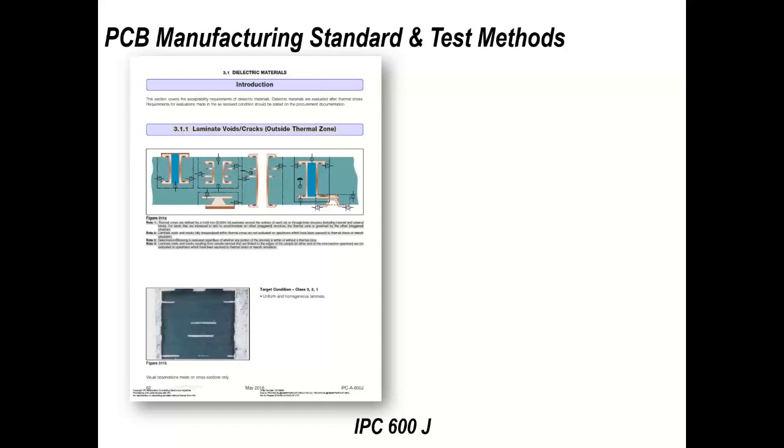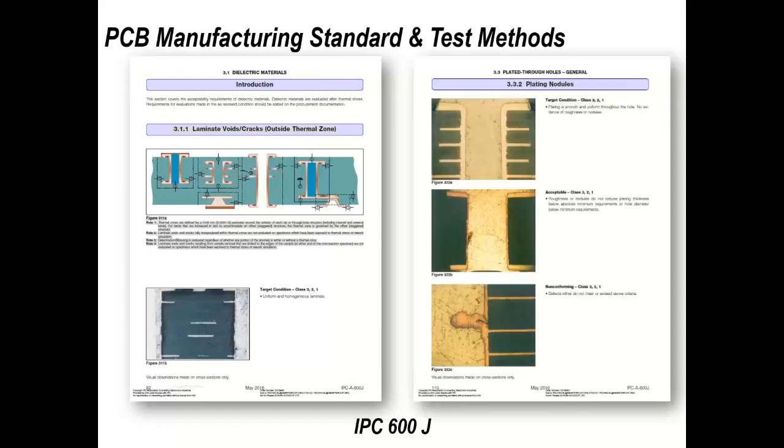You can take a microsection, which if you're doing it yourself, that's fine. If you're having it done for you, it may cost you 200 euros. You can then spend a lot more money re-grinding, re-cutting that sample to get a lot more data and information, and that can go into the thousands of euros. It just depends what you want from that investigation.